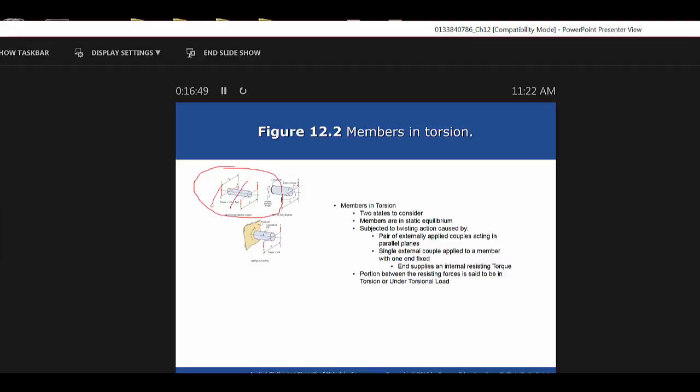All right, Howard? Distance between two forces should be perpendicular, or maybe any distance? They have to be perpendicular forces, right? So if you've got some force that's not perpendicular, then you're going to have to break it out and figure out how much is applied to that torque. Is that what you're saying? The distance D is the perpendicular distance between. That's correct. Perpendicular to the forces, yes.